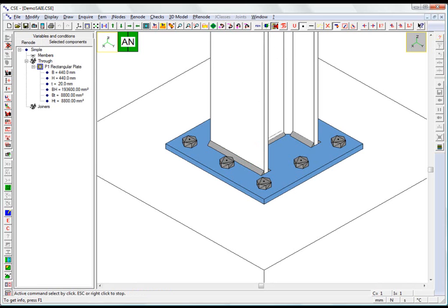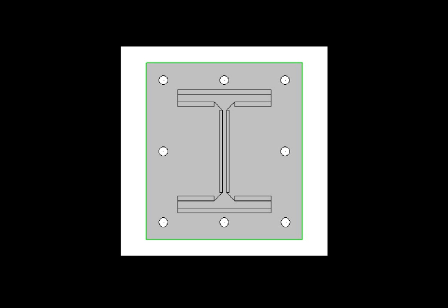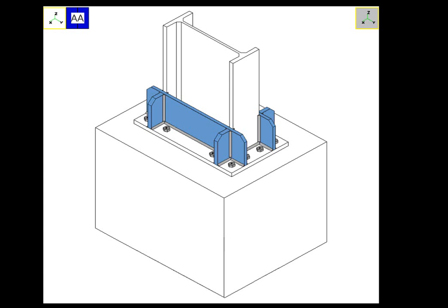In this case, the bearing surface can be the entire surface of the plate to which the bolt layout is connected. A thin plate tends to bend easily, and only a small area of it in the neighborhood of the applied load footprint can fulfill the role required. We can improve its stiffness locally by adding stiffening plates to connect the plate to the member that causes the bending. If enough of these stiffening plates are used, then the entire surface of the plate, despite its thinness, can successfully transmit the normal stresses and can thus function properly.